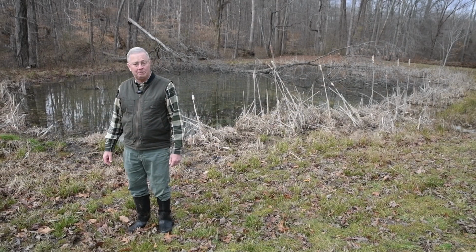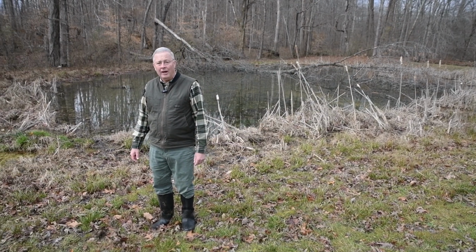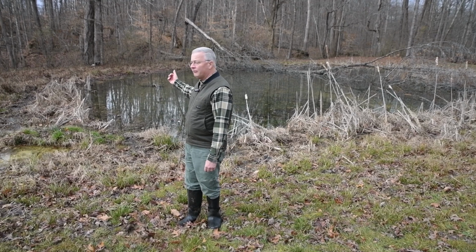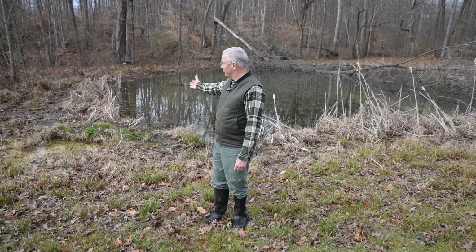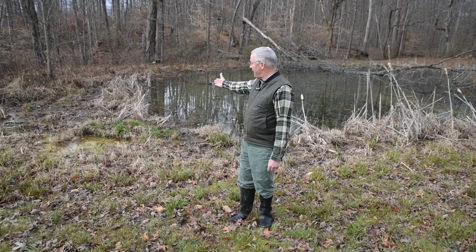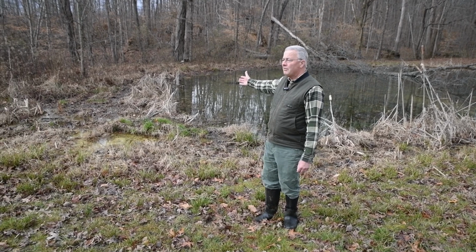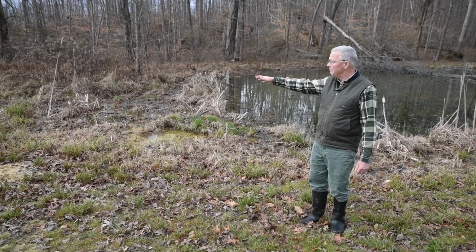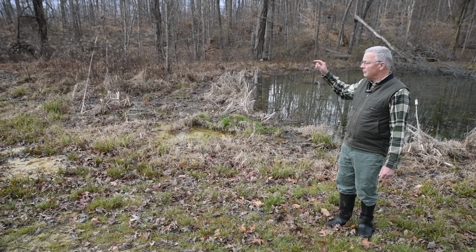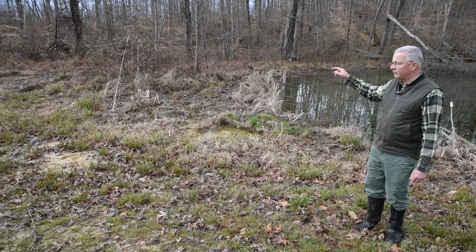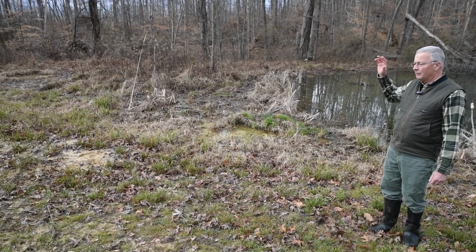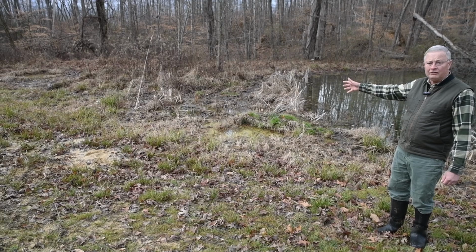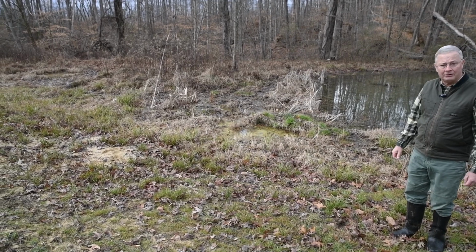We're looking at the spillway for a constructed wetland, and you see the way it's built is that it's very wide and the water flows over the ground in a sheet-like pattern. And when it flows over the ground that wide, it saturates the soil and it ends up making a wet meadow wetland. And there's absolutely no erosion. This wetland was built 17 years ago. The wetland looks great, the spillway looks great, and we have quite a bit of wetland habitat here.